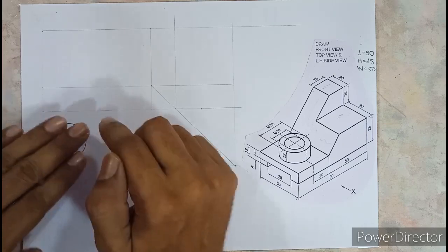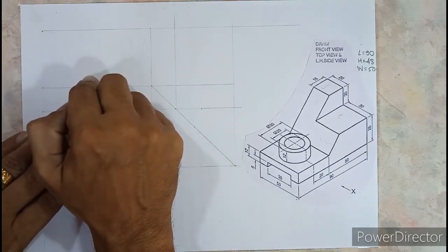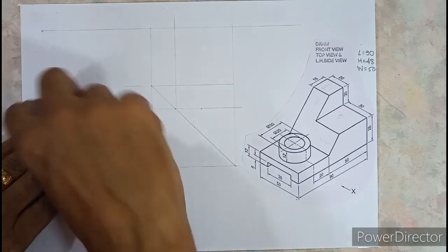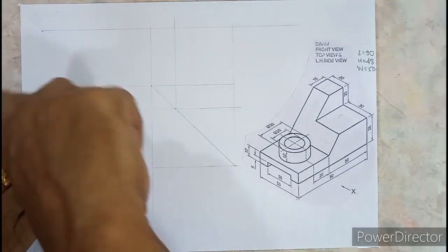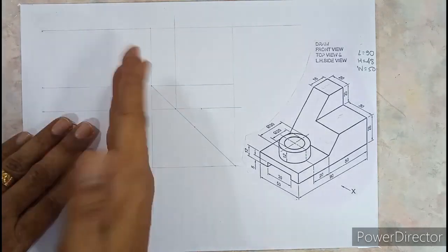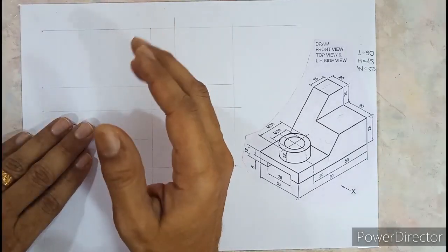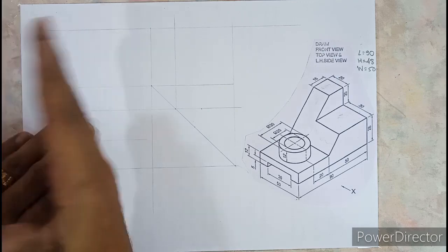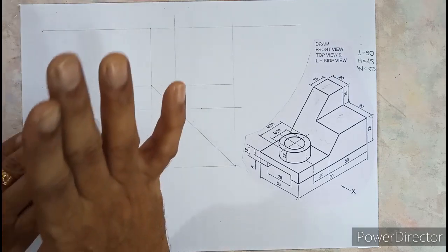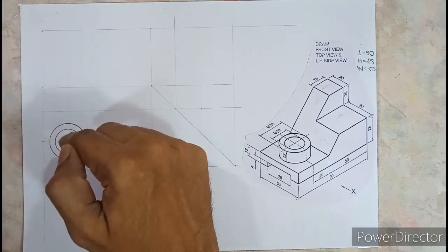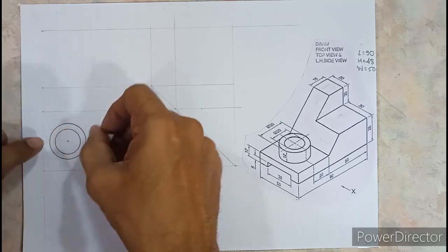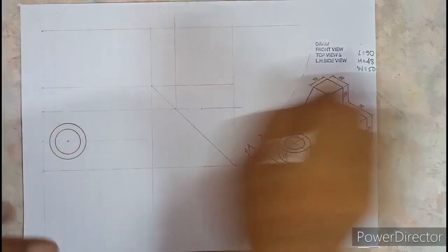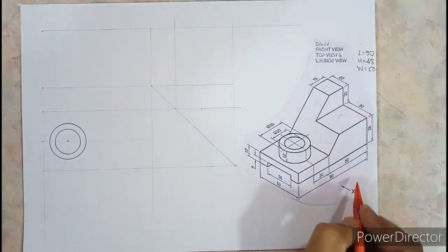Suppose if I don't draw circle first and if I draw a rectangle and then when I project, it is possible that after you project and when you draw the circle by compass, the circle might not touch both the projectors. It happens many times that when you take a compass and start drawing circle, it intersects one line and doesn't intersect the other line. So it is always advisable to do other way around. You first draw the circle and then project both the points up for drawing the other view. Anyway, let us start with the front view now.